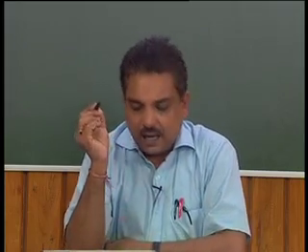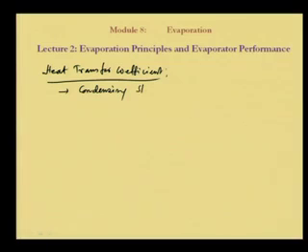One is that the tube fluid is getting heated, and on the shell side there is the steam. There is steam in the shell side, which is mostly a condensing steam, and the tube side fluid is heated. So, what happens is the condensing steam has got a very high heat transfer coefficient.